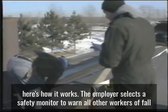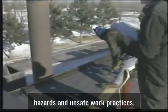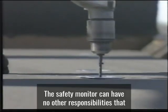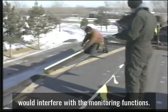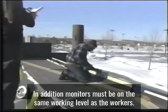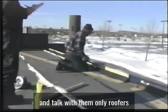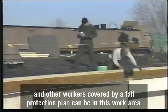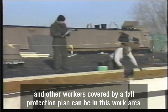The employer selects a safety monitor to warn all other workers of fall hazards and unsafe work practices. The safety monitor can have no other responsibilities that would interfere with the monitoring functions. In addition, monitors must be on the same working level as the workers. In other words, close enough to see them and talk with them. Only roofers and other workers covered by a fall protection plan can be in this work area.